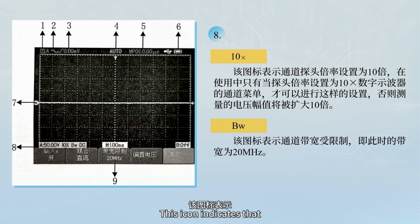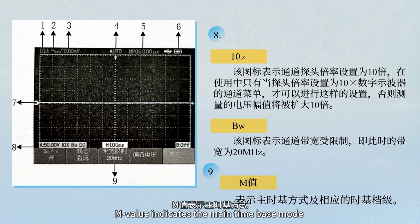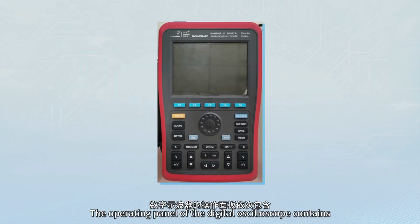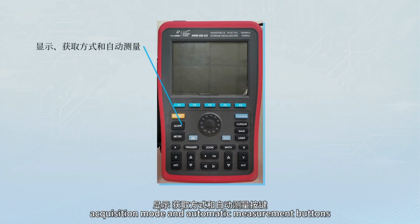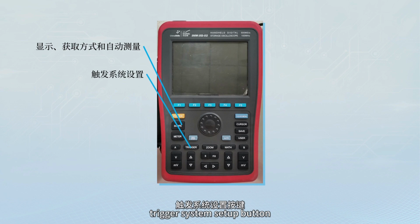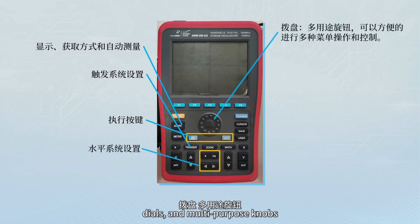This icon indicates that the channel bandwidth is limited and that the bandwidth is 20 MHz at this time. M value indicates the main time-base mode and the corresponding time-base level. The operating panel of the digital oscilloscope contains the power button, acquisition mode and automatic measurement buttons, trigger system setup button, execute button, level system setup button, dials, and multipurpose knobs.